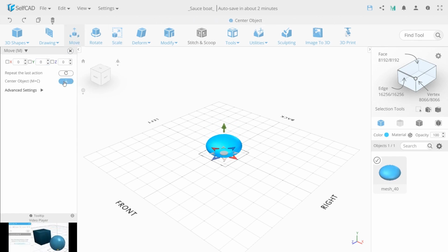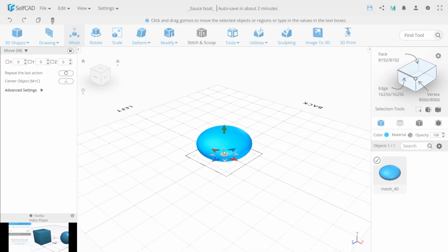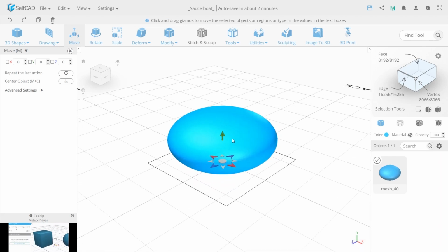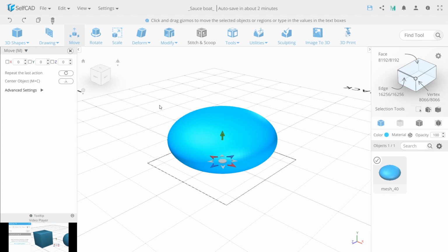As you can see, we use the same value of 64 for the original sphere and now for the scaling as well. And that's because the initial value was in radius while scaling uses size. This means that the size of 64 is the same as a radius of 32, hence making the height half the size of the other two dimensions.